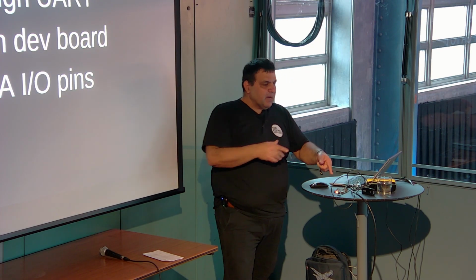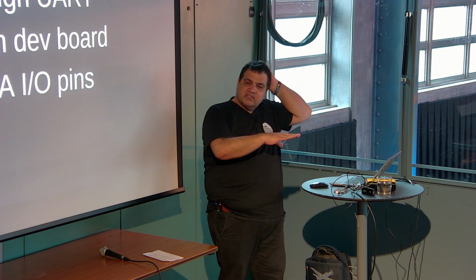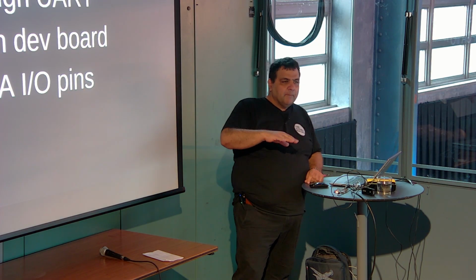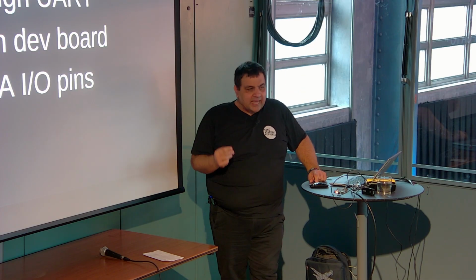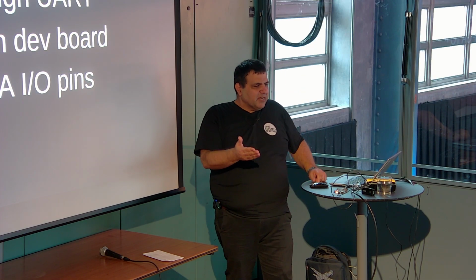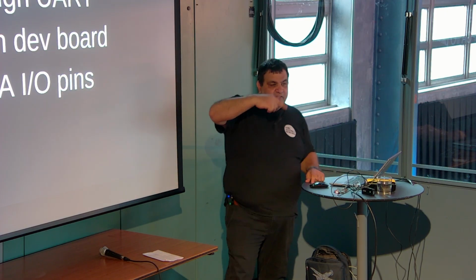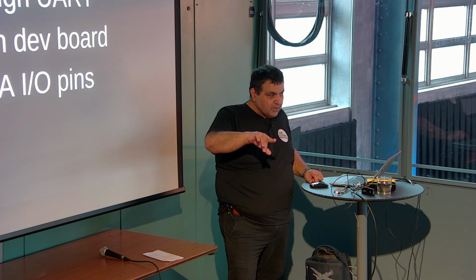We have 3 buttons on the board itself. One of them resets the FPGA itself, so it's not programmable. But one of the other 2 is labeled reset. Now it doesn't matter, it's just an I/O pin, but we might as well hook it up to the 6502's reset line.